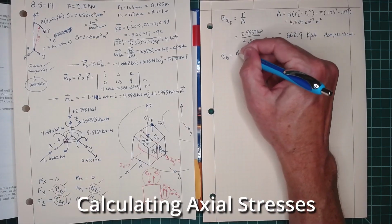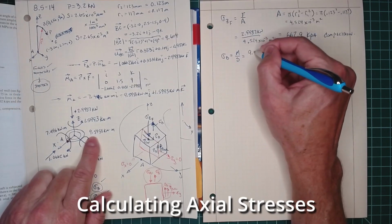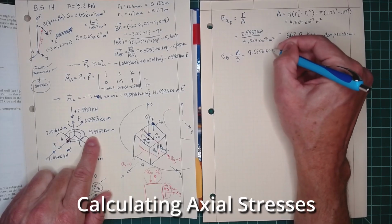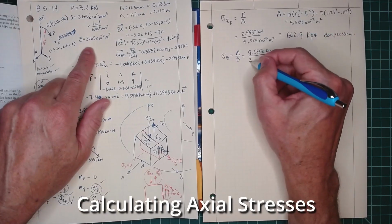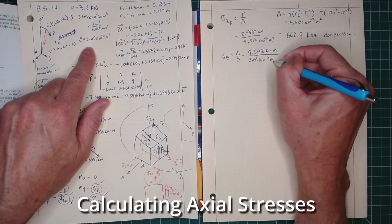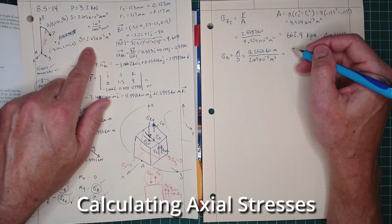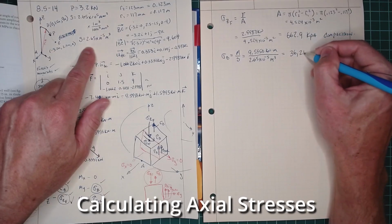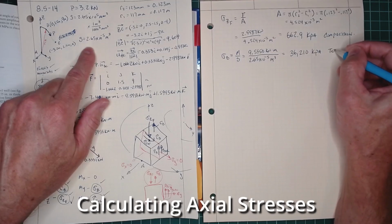And we know the equation was M over S. In this case, the moment is 9.5958 kilonewton meters divided by our S, which is 2.65 times 10 to the minus 5 meters cubed. We can plug all that in, and we end up with a stress of 36,210 kilopascals, and that is in tension.